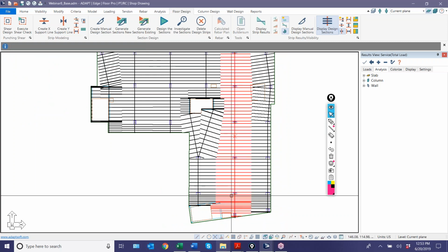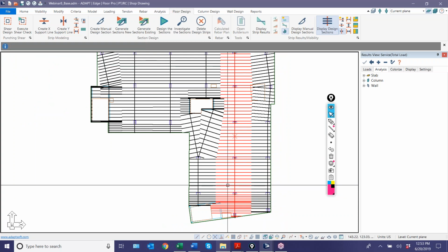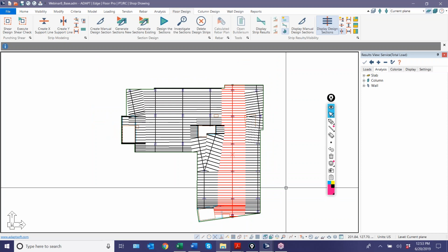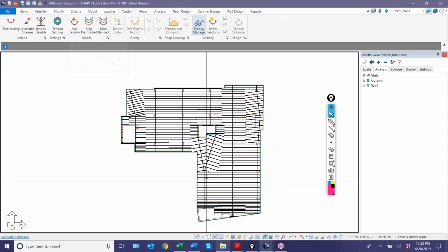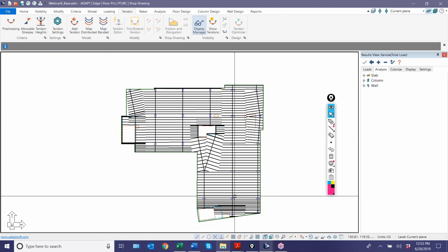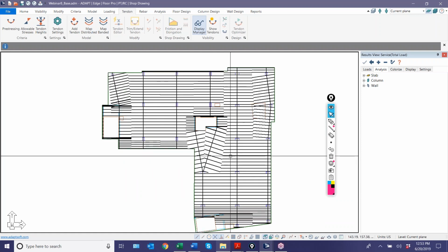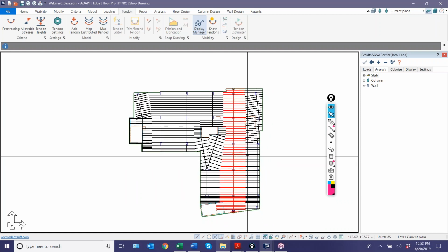So we'll take the 325 and divide it by our assumed effective force of 26.5. We need 12 or 13 strands in this strip. So now I have to go back under tendons, add the tendons, assume a CG. I might max out the CGs unless I have very short spans and I know that I'm going to raise the profile so we don't overbalance the load, the dead load in the span. Or I can use the mapping tool, which tries to target pre-compression and balanced loading.